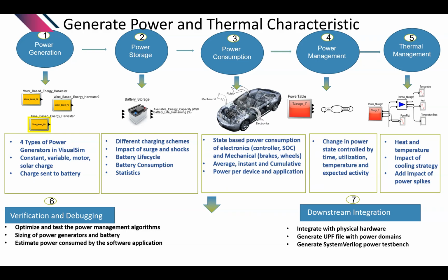Now, one of the key things for an SoC designer is that the power system in VisualSim does not just tell you what your power consumption is. It also generates things like UPF files, SystemVerilog files, and VCD test benches, so that you can use that either to verify your downstream, but also to test the implementation of this power management system.